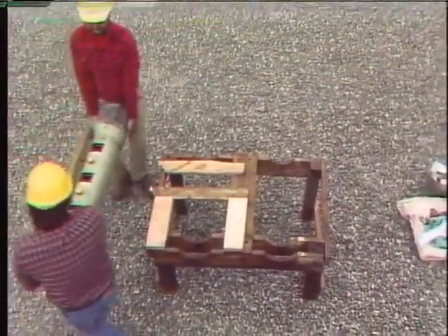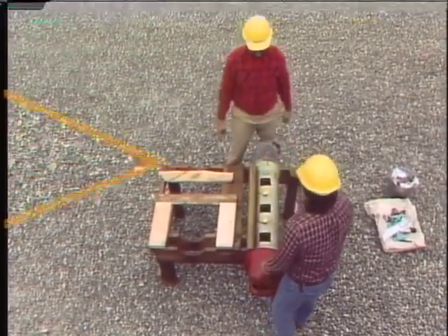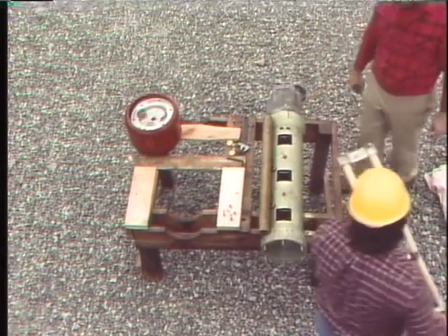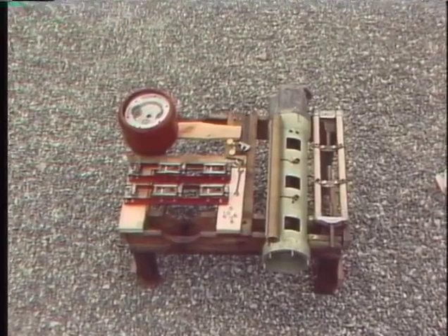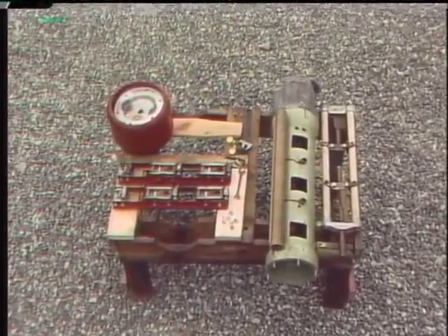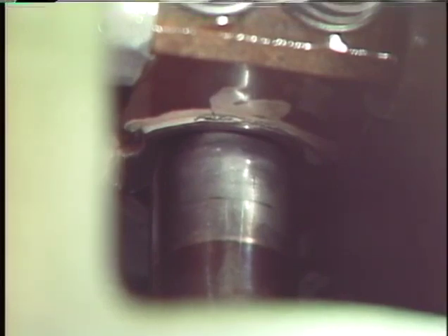Before the grids are reinstalled, the contacts are inspected for signs of wear or damage. It may be necessary to remove the interrupters and disassemble them in order to thoroughly inspect and clean the contacts. After the contacts have been inspected and cleaned, the interrupter will be reassembled and reinstalled in the breaker tank. However, before the arcing grids are reinstalled, the contacts are checked for initial contact engagement and alignment. Contact penetration is also checked. Penetration is a measurement of how much of the moving contact makes a good, firm connection with the stationary contact.